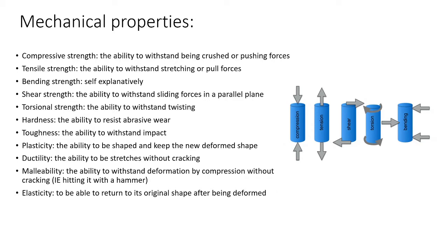These next two slides you have definitely seen before in previous videos, so we'll go through them again just so you understand what they're for. Compressive strength is being able to withstand crushing or pushing forces. To put that into the context of a product in a question, it might be asking why stainless steel has been used for the legs of a chair. It needs good compressive strength, because if something has poor compressive strength, then when I sit on the chair and push down on it, the chair breaks. Useless chair.